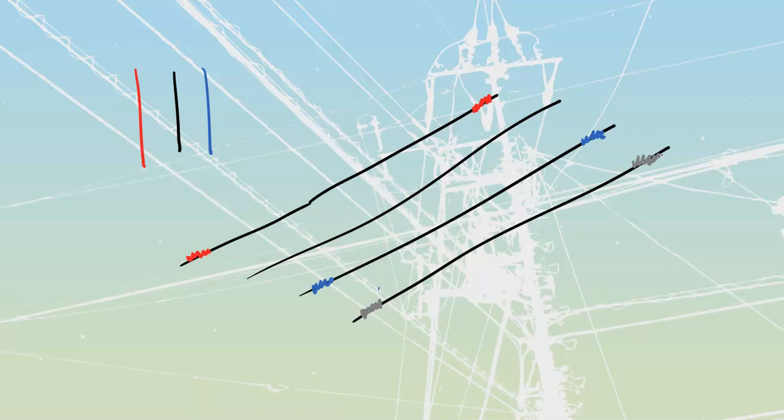MI cable is just going to be a continuous copper sheath, and inside of that it's going to have a whole pile of powdered mineral. That's where it gets the name, and then it's got bare conductors inside. But when you terminate them, you are going to place colored sleeves over top of them. Because of its construction, it does get a pass on this rule, the 4026 that we were talking about, where we have to phase identify everything, that it's going to be larger than number 1. Anything smaller than number 1, so number 2 and downward, has to be an actual continuous color, other than the MI cable.